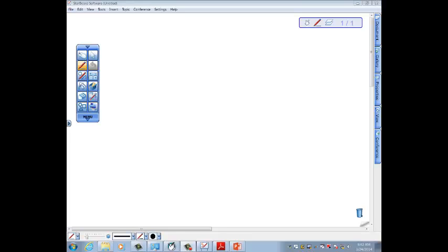Oh, I see what you're looking at. Those are the hooks. They're not talking about that. That's not the size. When you talk about a bar size, it's in eighths of an inch. So a number 5 bar is 5/8 of an inch. A number 9 bar is 9/8 of an inch, so that would be 1 1/8 inch. So you want to try to draw your bars to that scale.